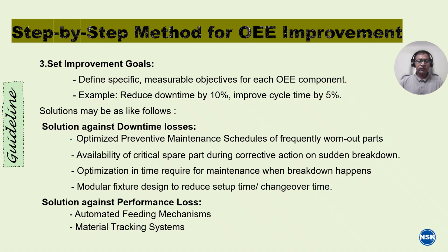Solutions may include solutions against downtime losses: optimized preventive maintenance schedules of frequently worn-out parts, availability of critical spare parts during corrective actions on sudden breakdown, optimization in time required for maintenance when breakdown happens, and modular fixture design to reduce setup time and changeovers.